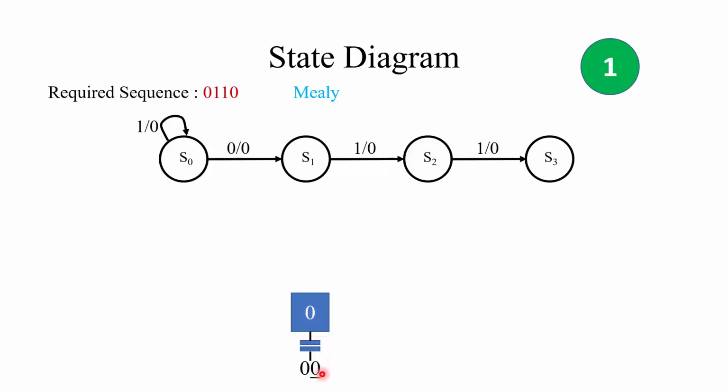If this turns out to be a match, our next state will be S1, we can stay on the same state. And if this comparison turns out false, then we'll have to transition to the reset state. In our example, this comparison is true. This means we'll stay at S1 and we'll keep our output low.